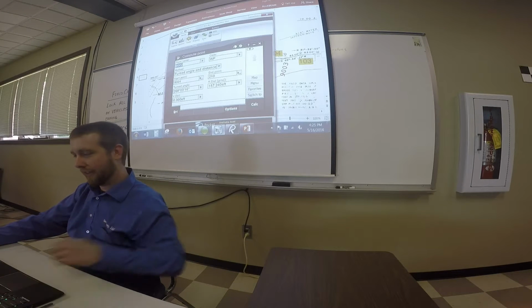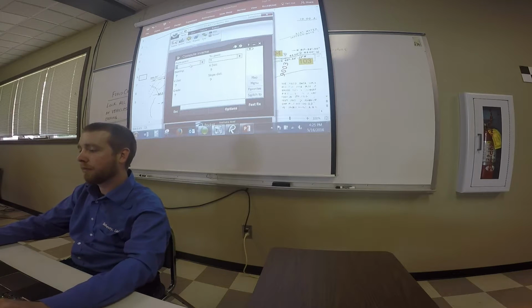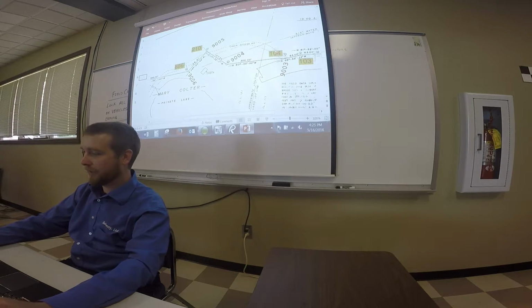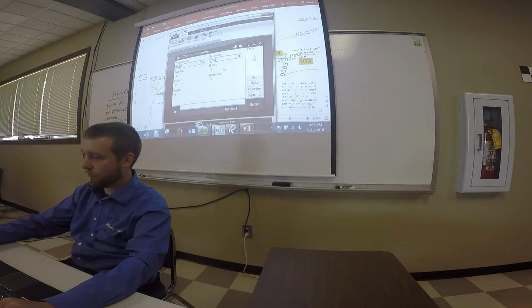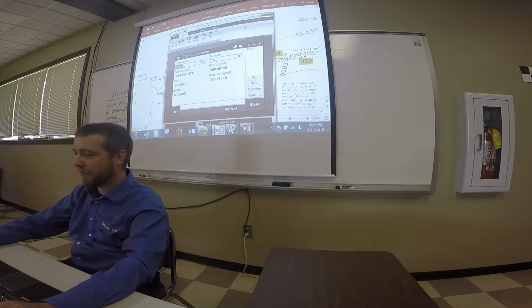Okay. And then again, most important thing is we check it. Go to COGO, go to inverse. It's punched in 9001. Now we'll inverse. So we'll check it against this pin way over here, 104. 299.86. So it checks good.